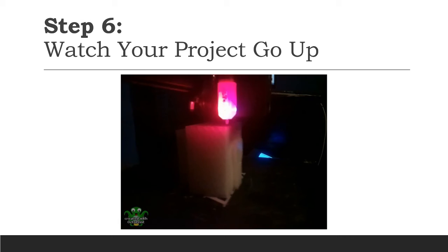So according to Ultimaker.com, the best way to remove supports is to submerge it in warm or hot water so it breaks down a little bit before you remove it. So that's what we're going to do. Make sure not to hold it in there too long or else it will melt the entire thing.